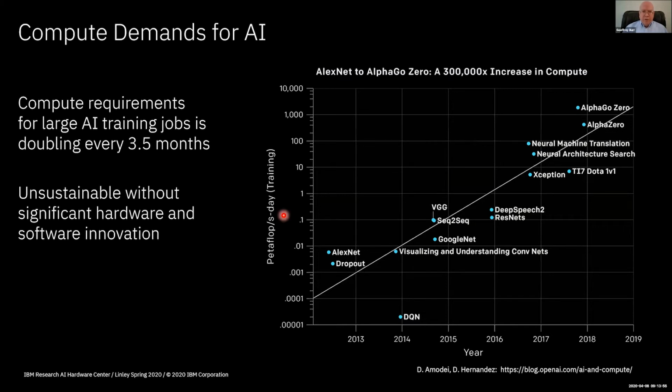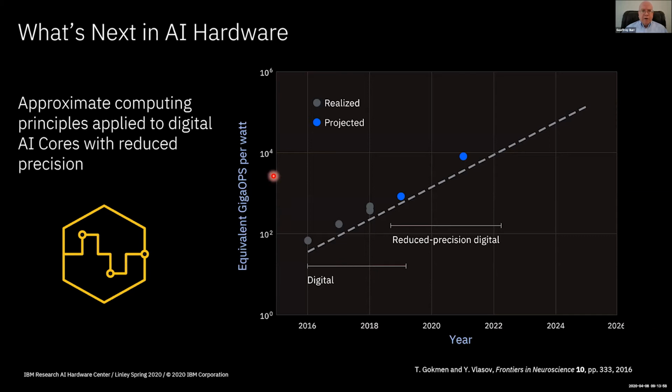So what we really need to do is to continue to improve this curve of gigaops per watt. We'll still need to do those many teraflops. A teraflop is about right here between 10 to the 2 and 10 to the 3. So this is a teraop per watt, and that's right about where products are coming out. They're already exploiting reduced precision. We're already seeing most products for training talking about bfloat, and most products for inference talking about 8 bits.